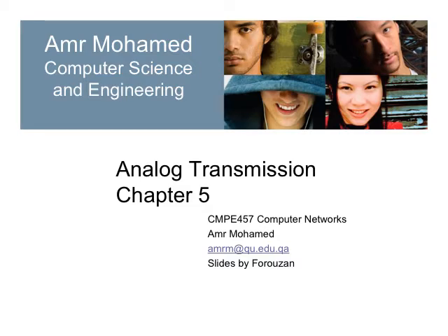Not only do I have to get rid of the DC component in that case, I have to shift the whole signal in the frequency domain very far away from zero. Okay? So I cannot afford to have any low frequency at all. So the channel itself will have a specific bandwidth which is shifted away from the zero.